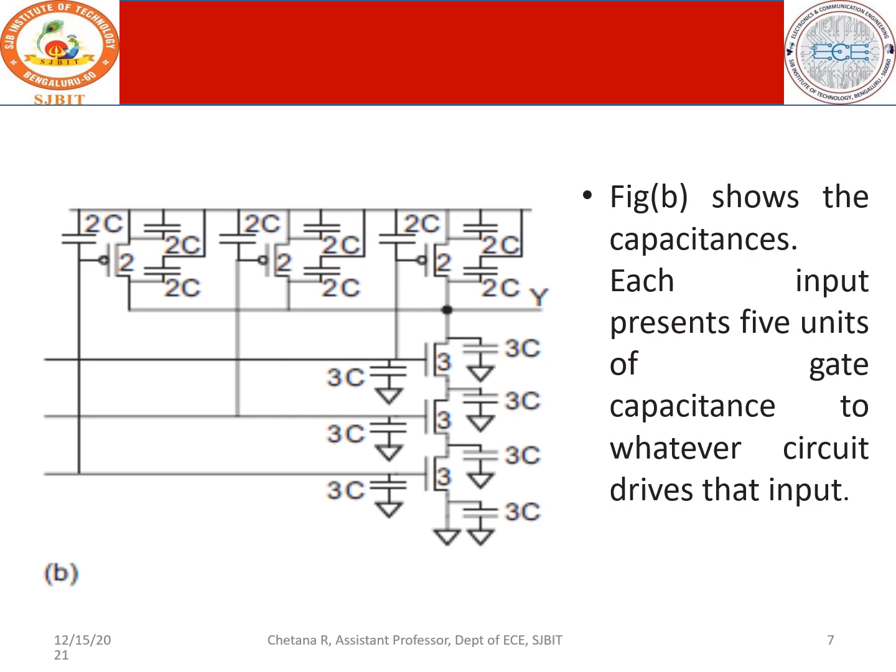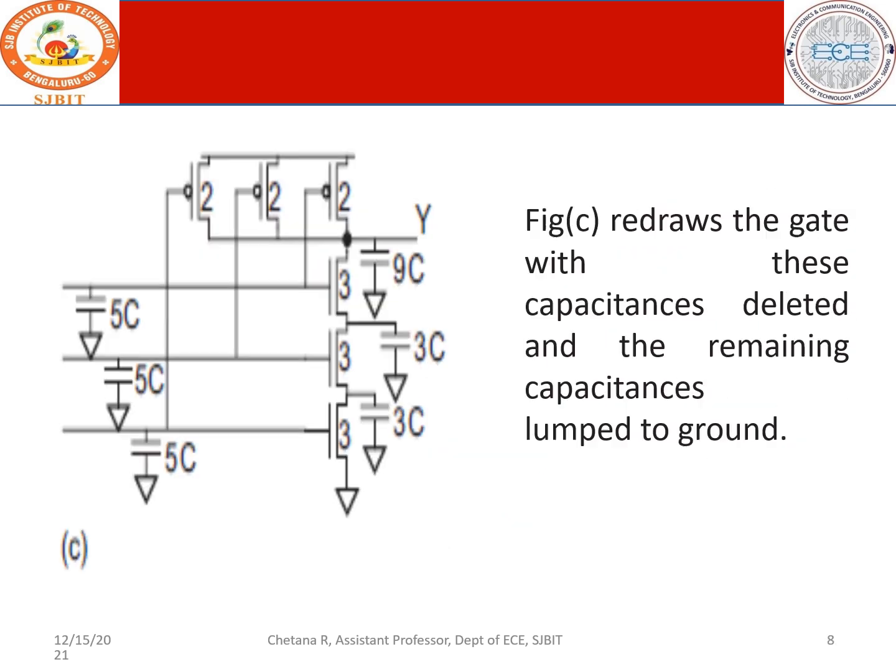We will simplify this by considering a common node, since the gates are commonly connected to the input. So the gate will have 3 plus 2, 5C, and the next diagram shows you. So 3 inputs are common, and therefore 3 plus 2 will give you 5C. Gate capacitances for every device is considered here as 5C, and the ratios remain the same.